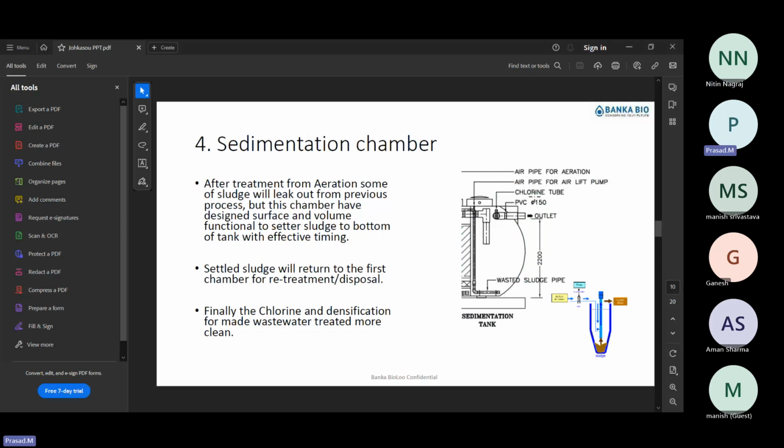Because sometimes what happens is, when your chlorine tank is empty, you change the chlorine tank, remove the pump suction, and insert it into the new tank again. At that time an air lock will happen and the chlorine dosing will not happen. As well as electricity, no doubt electricity use is very low for a pump, but this point I would like to highlight: there is no air locking, and you can disinfect your water continuously by using chlorine tablets.